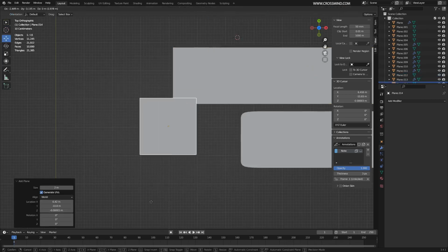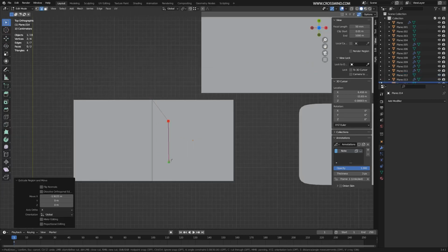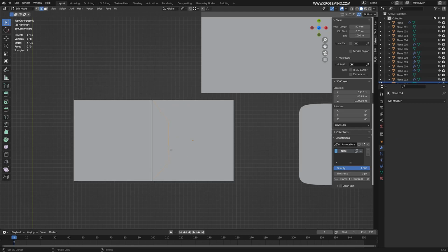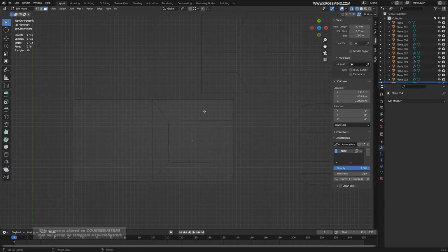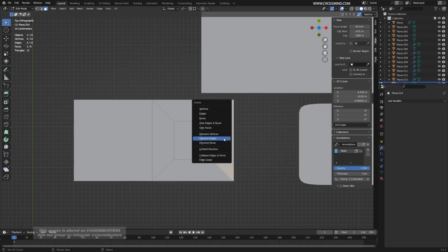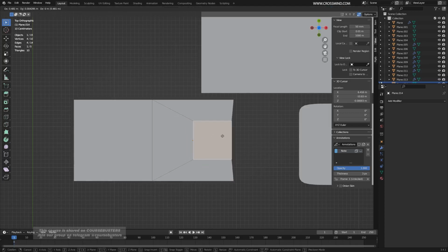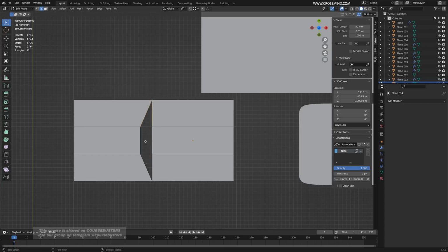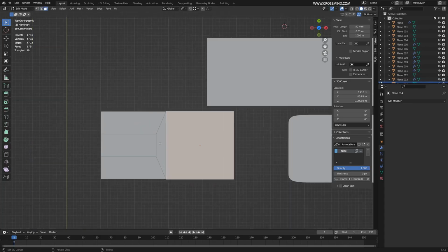Now let's try this one more time. You can simply make one cut like this. Just remember this pattern and then you can connect it through and through, and this will subdivide it. So you have quads and you have more resolution. Or you can simply inset this, delete one side and then move it here. Now you have more resolution. Or you can simply add two loops, rip this apart, fill this area, and now you can get rid of these, and there you go. So based on the scenario, you can use any of the methods.